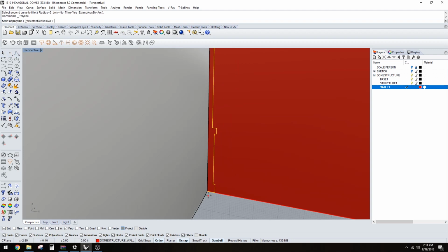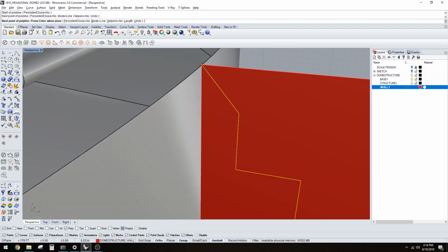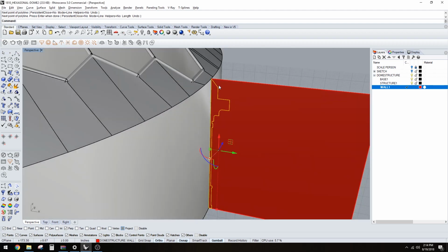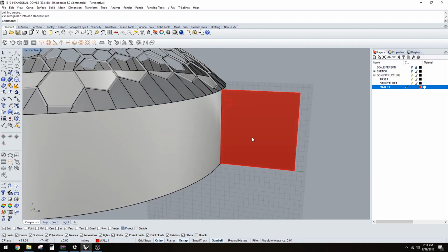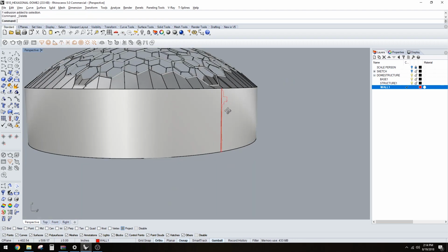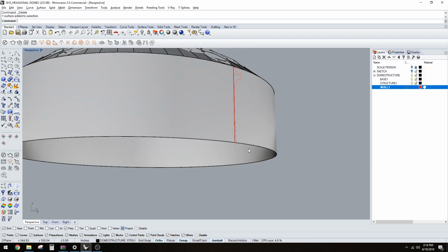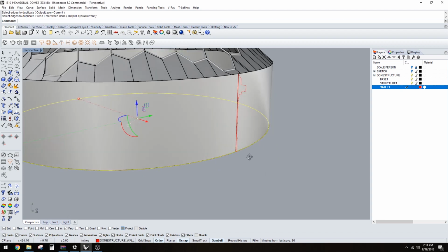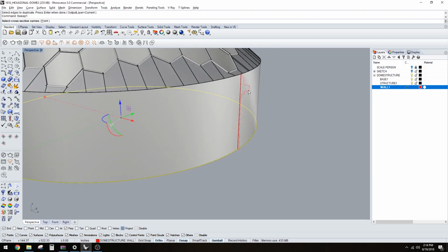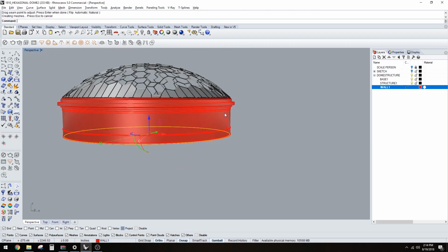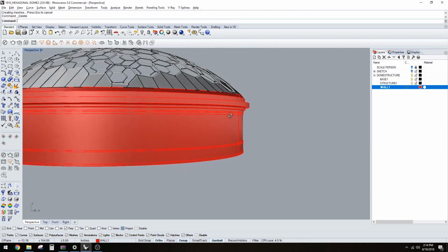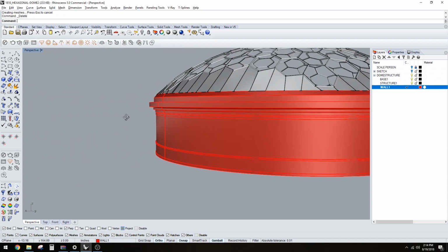profile that actually I would like to close off, so you have a perfect curve. So now you want to put the C-plane at the bottom again, delete that, make sure you have that bottom, that base edge, so duplicate edge, dupe E, there we go. Now we have that, and we can go ahead and sweep 1, select that. We have a nice base structure for this dome.